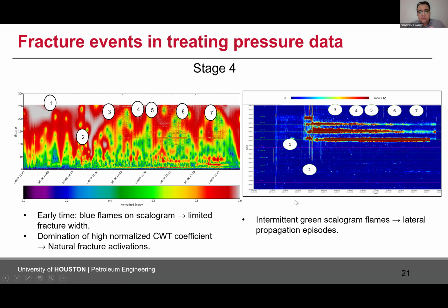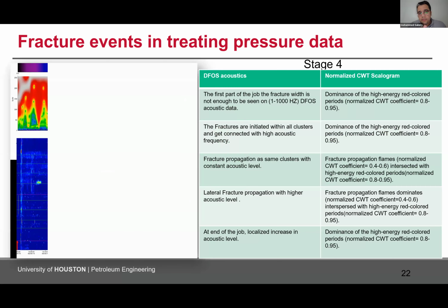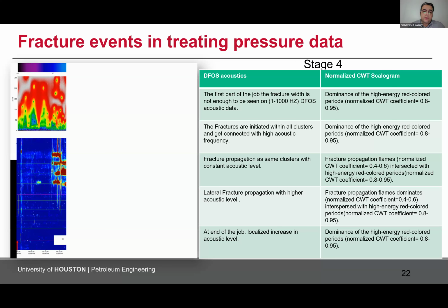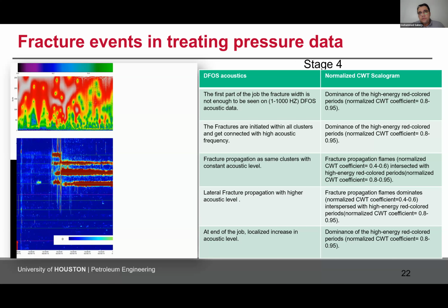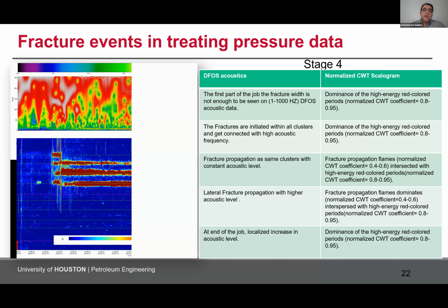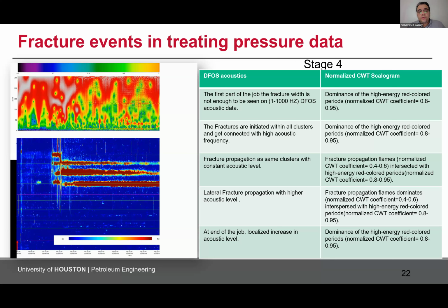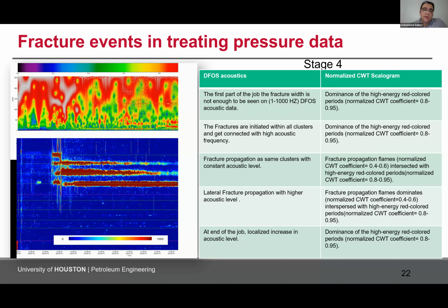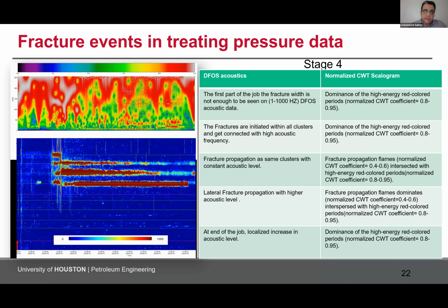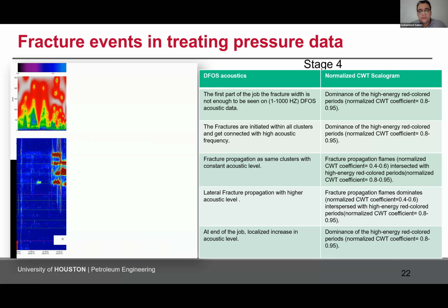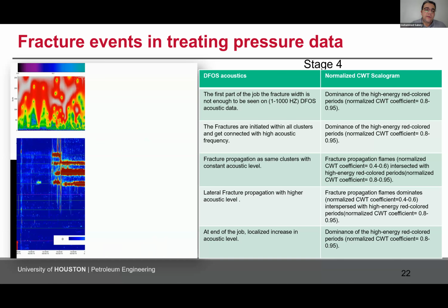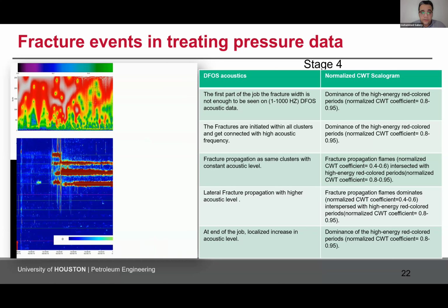And that's what we got specifically when we compared the scalogram and the acoustic data from the fiber optics. Here's also the video that represents the comparison with the scalogram, because it shows the fracture propagation during the hydraulic fracturing job, and how it performs downhole in fiber optic sensing. And that's how we can get the fracture propagation events by this comparison.